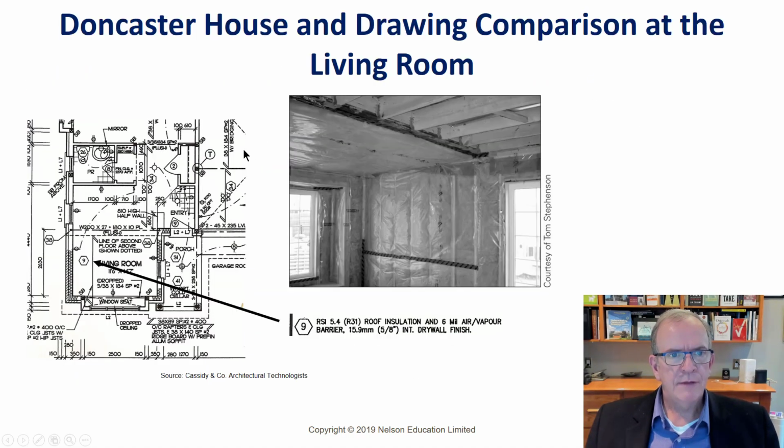So it kind of gives you the intro and the idea about how that works. And as I mentioned, this is the Doncaster house. So this is that close-up of the living room here. There's essentially a roof over this section here, steel beam going across. These kind of intersections, they are always difficult to really tightly seal. And that's a challenge. And as we move to net zero, those things get to be more challenging, but more fun in a lot of ways too.